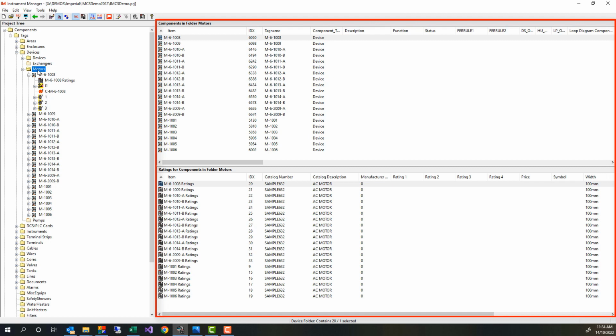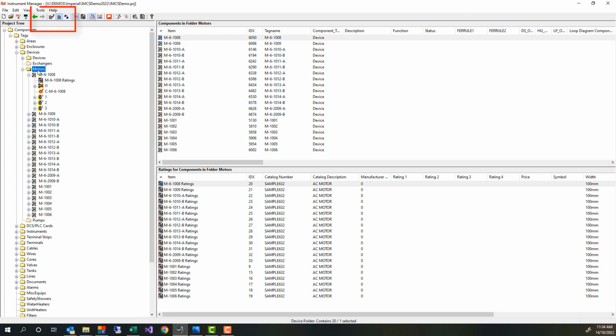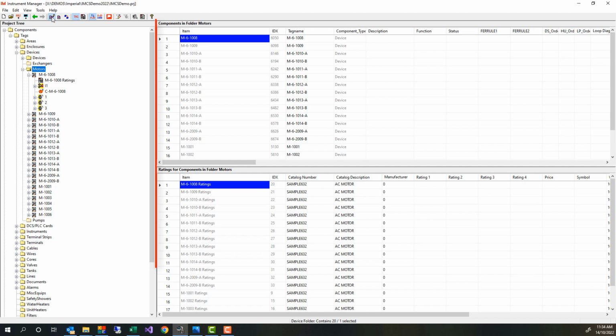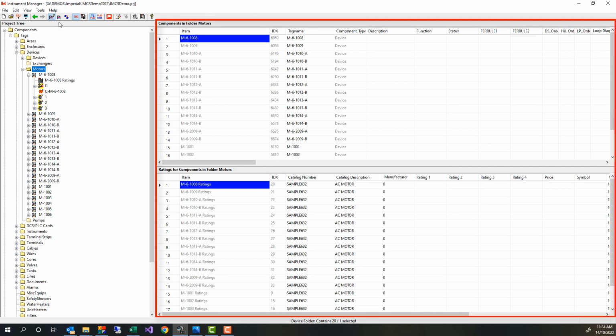With the components in the list view, you can select a specification from the catalogue, add a datasheet or loop, and globally edit components. If I click on the toolbar button displaying the pencil, I can switch to an edit view. The edit view allows you to do basic editing commands on one or more components. These views can be sorted and filtered using the title bar.